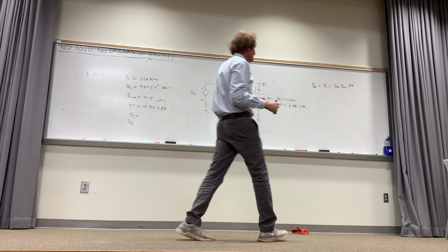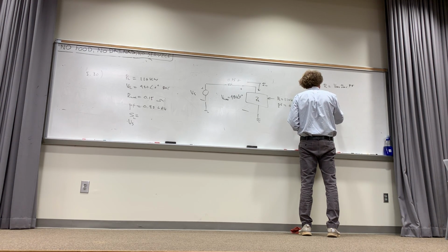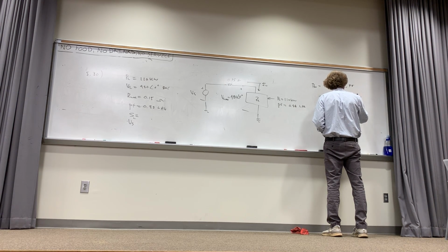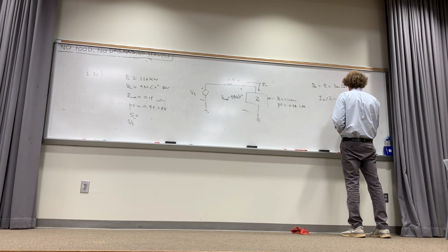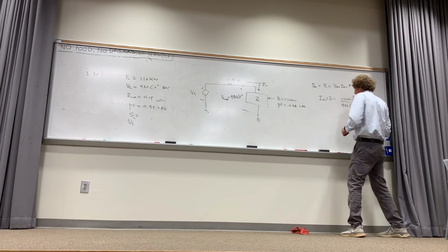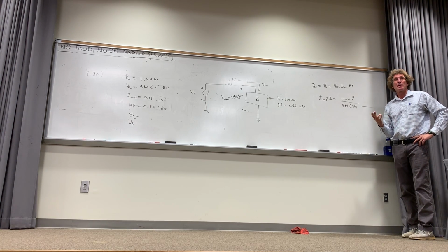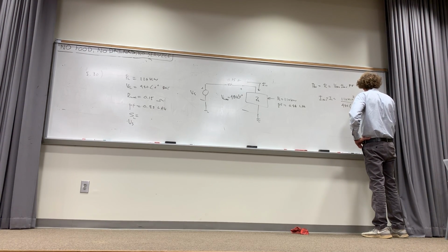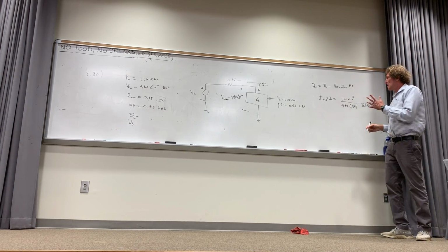So now we can calculate the magnitude of I directly. IRMS, which is I line, they're the same thing, is equal to P, which is 110 times 10 to the third, divided by 480, the line voltage, divided by the power factor, 0.88. What do you get for this magnitude of I? This is only going to be the magnitude. Anybody? 260.417. How many got that? It's a straight division thing here, nothing tricky.